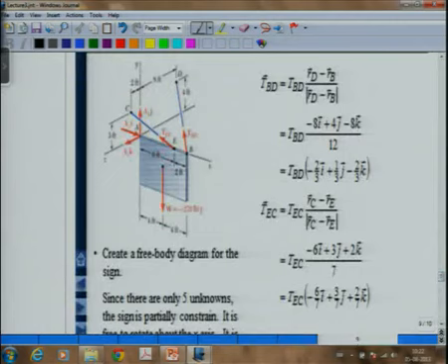So, first we draw the free body diagram. At the point A, there is a pin, that means at A we will get an unknown force with some arbitrary direction, which we write as Axi plus Ayj plus Azk. 3 scalar components. Unknown force with arbitrary direction means in a 3-dimensional case 3 components, and we obviously choose, as you will see in this course, we are following a vector approach, makes life easy. So, we will put everything along x, y and z. So, at A we put Axi plus Ayj plus Azk.